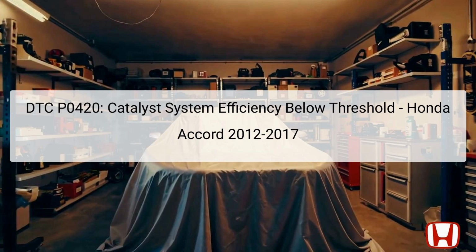The Powertrain Control Module, PCM, monitors this process by adjusting the air-fuel mixture and observing the secondary heated oxygen sensor, secondary HO2S. If this sensor indicates that the performance is deteriorating over time, the PCM records the fault and sets this DTC. The monitoring process occurs once per driving cycle and is sensitive to various operating conditions, such as engine